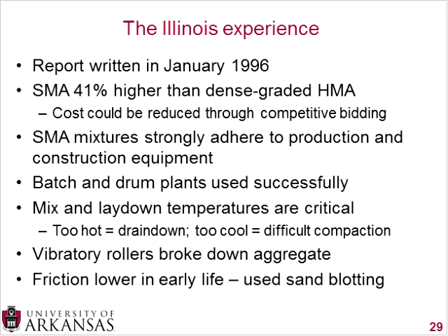The Illinois group found that the SMA mixtures strongly adhered to both production and construction equipment. So this is going back to what I was saying with the pneumatic tire roller. You don't want to use pneumatic tire rollers because of pickup. In general, SMA is pretty sticky, and so it will adhere to both your production and construction equipment, so you do need to be careful with that.